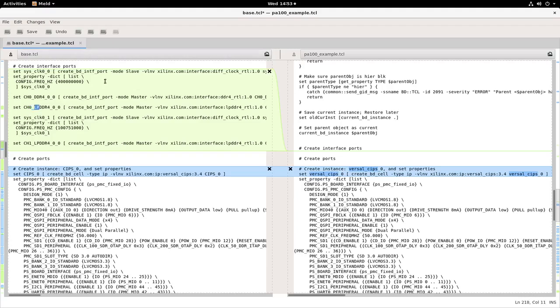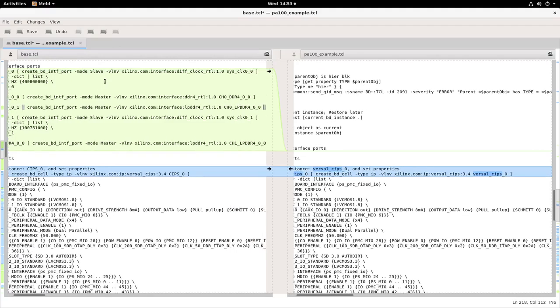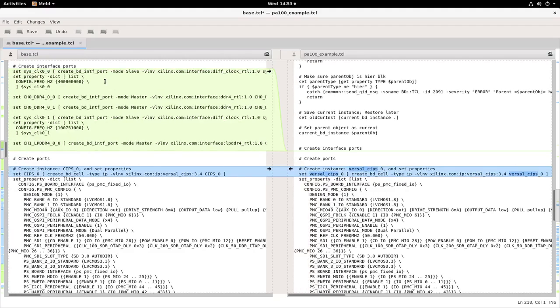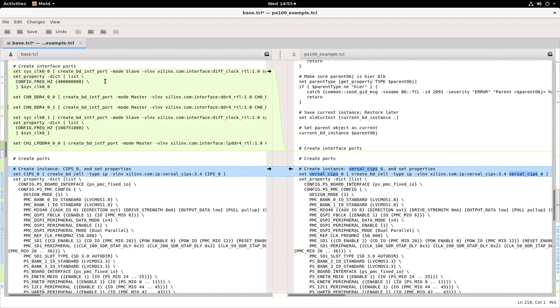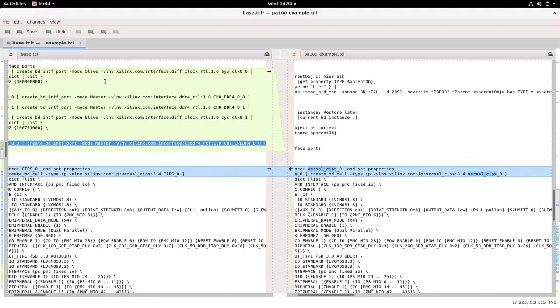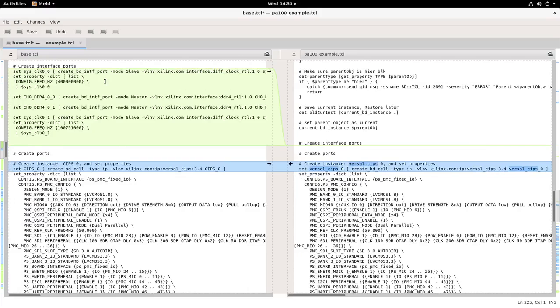So we'll just rename the ports to a new DDR port instead of the LPDDR, and the interface definition in Vivado needs to match that type of memory. Other than that, it's just giving a different name and wiring it up later in the script. So let's check that we don't have any remaining connections that are hanging.